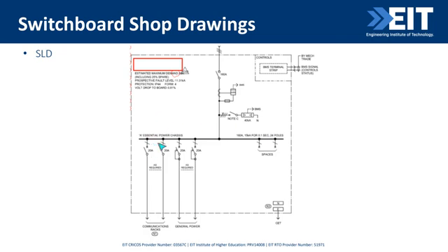We're also shown we've got single phase outgoing supplies with 20 amp circuit breakers. These two have RCDs, so we would check those as well. It's an IP44 and a Form 4 board with a neutral and an earth bar and a controls section. So you could highlight off each of those parts against the shop drawings to make sure nothing's been missed.